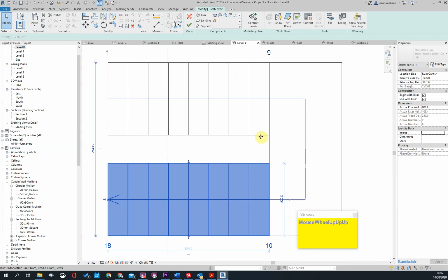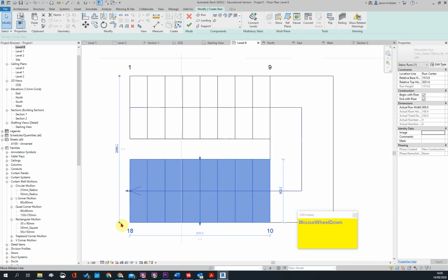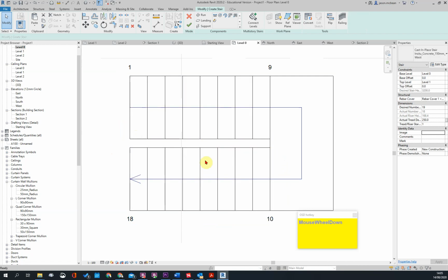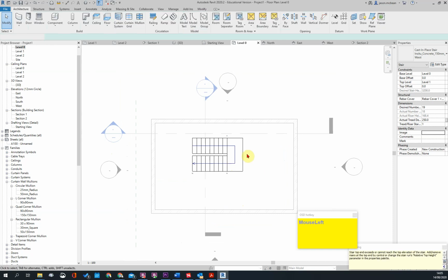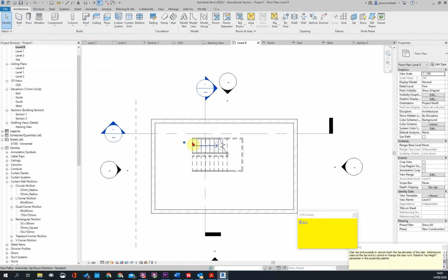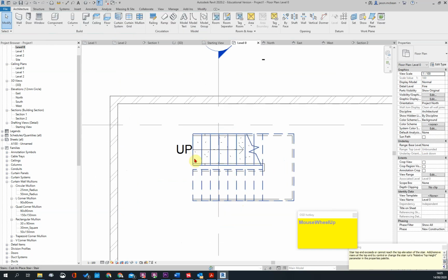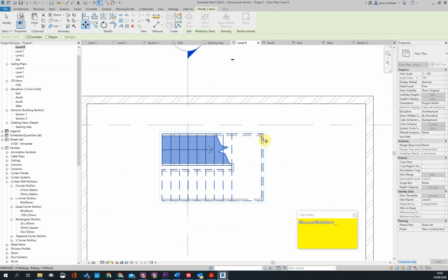And generally, I leave a 120 mm gap in the middle because you want your hand railing, you want comfortable space for how the hand railing wraps around the corner. So I'm going to finish this and I'm going to move the stair into the corner. I'm going to move this. I'll move my shaft now.